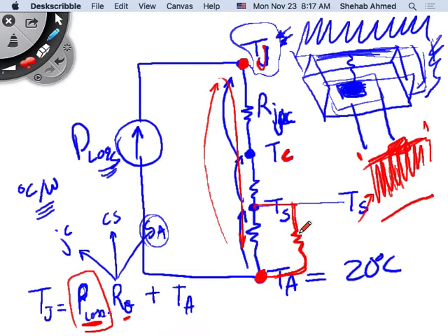Okay? So here, if this is a large number, like let's say 100, and I've designed this to be 10, these two resistors are in parallel, right? Which would be more dominant? The small one, right? You have two resistors in parallel. What's the equivalent value of resistance? The smaller one, right? And if you have 100 ohms and 1 ohm in parallel, what's the equivalent value of resistance? 100 times 1 divided by 101, so it's about 1.